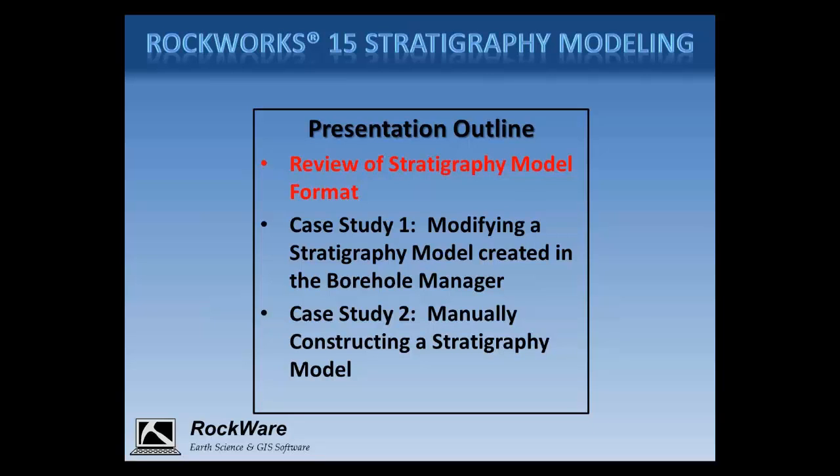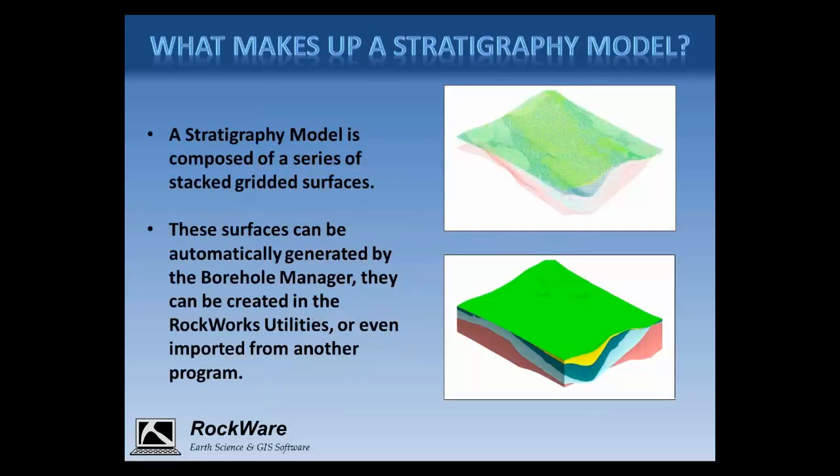The first thing I want to review is how a stratigraphy model is structured in RockWorks15. A stratigraphy model is composed of a series of stacked gridded surfaces as illustrated in the image at the top of this slide. When displaying the model in 3D, we add side panels to fill in the gaps between contacts and display it as shown in the image below. If a unit pinches out, it can be rendered transparent in areas where it doesn't exist.